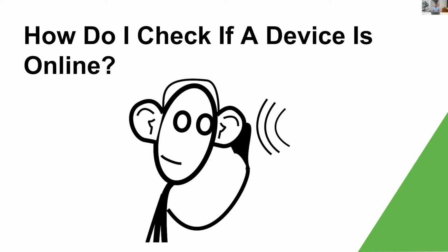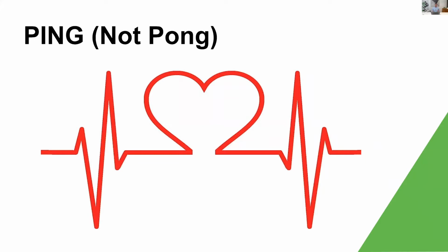Well, there is one very, very simple block that I can use that does everything I need in this scenario, and that is ping. Ping is a general network term for sending a packet of data to an IP address and seeing if you get a response. We have a ping function block within LOXONE Config that, as long as our mini server is connected to the network, can start pinging an address somewhere.